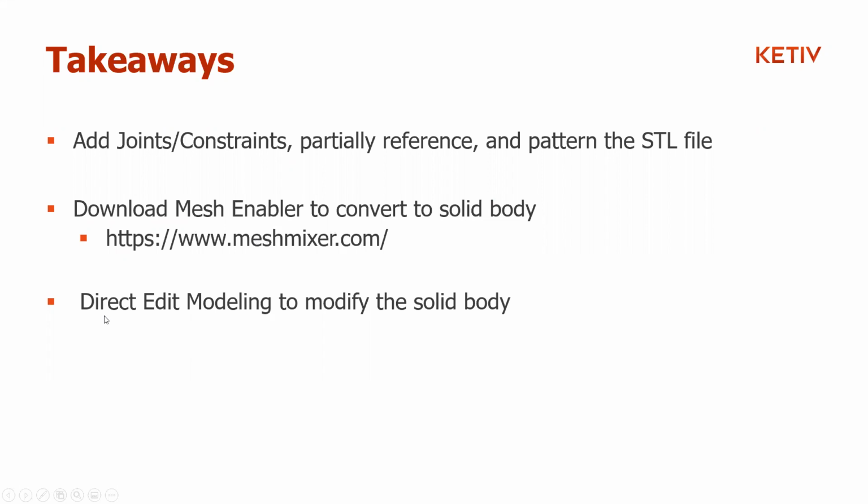And then lastly, once you convert it over to a solid body, you can have direct edit modeling tools like the ability to select those faces and then have it heal itself, or use the surfacing tools to patch and stitch itself to edit the solid bodies of the STL files.